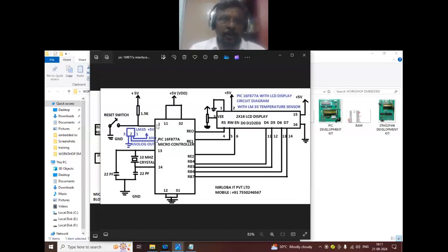the task. Suppose you want to restart the microcontroller due to some hanging or any other problem. For that there is a switch, called the reset switch. In this reset switch, one pin is connected to ground and the other pin is connected to pin number 1. So if you press the switch, ground is shorted to pin number 1, which means the pin becomes low. If the reset pin becomes low, your microcontroller will restart. So this is the reset circuit, the first one.